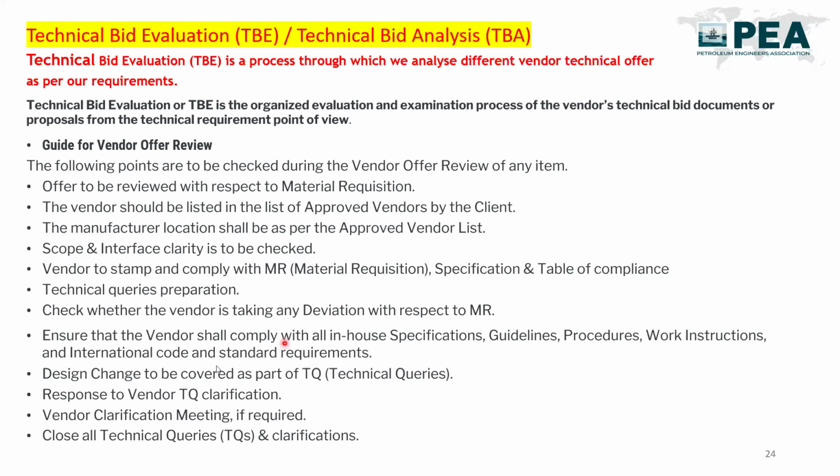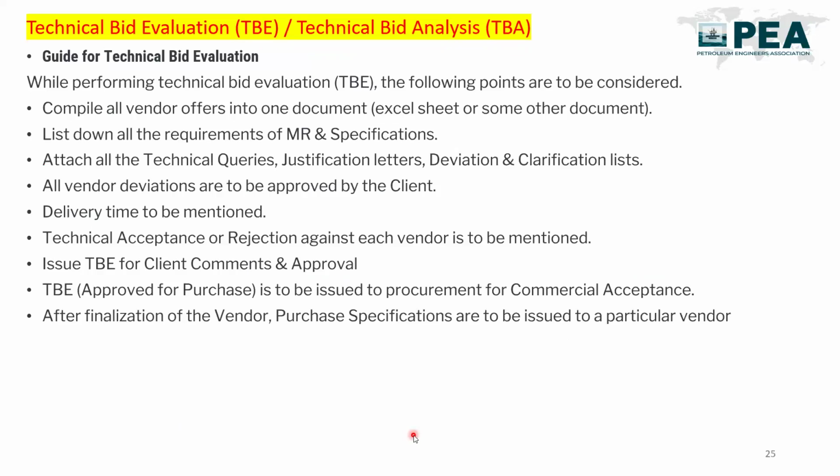Design changes are to be covered as a part of the TQ. If the vendor is changing any design from our requirements, that should be covered in the technical queries. For the TQ clarification point, the vendor has to give the clarification or a proper justified answer to the technical queries we raise, and that TQ will be part of this TBE. After this, if required, we will also hold a vendor clarification meeting. And after all these activities, we will close all the technical queries or technical clarifications we are doing with the vendor.